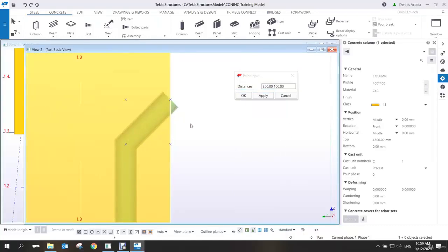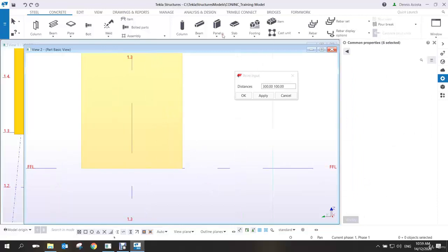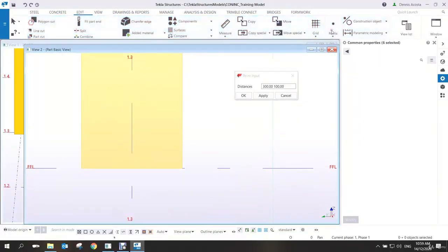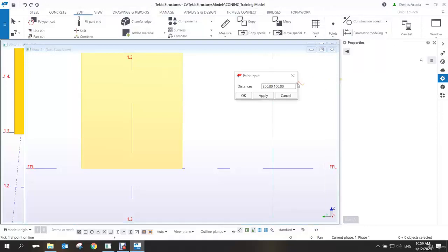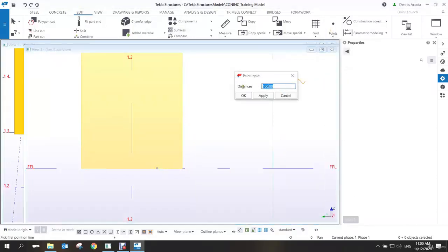Okay, can you try this one first? Maybe let me repeat again, quickly. So first, go to the edit, add the points, a long extension of 2 points, which is 100, apply. So I'm going to add this 100, and then parallel to 2 points, I will type here 300 and then 100, apply.